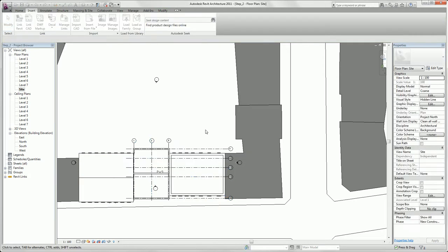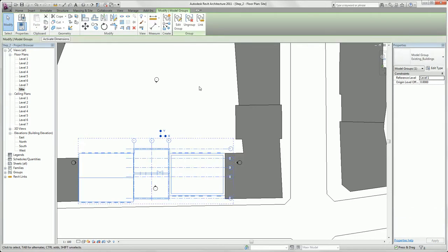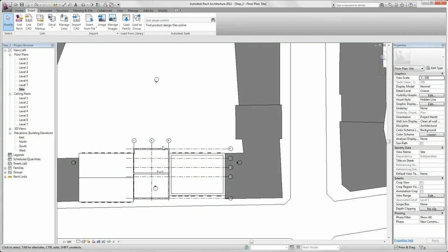Now those buildings are bound to our Revit project, therefore the file size increased. If you unlink a project, it's automatically grouped. We want to ungroup it. We click escape, select it. We choose here ungroup. Now you can use all elements and change it at any time.